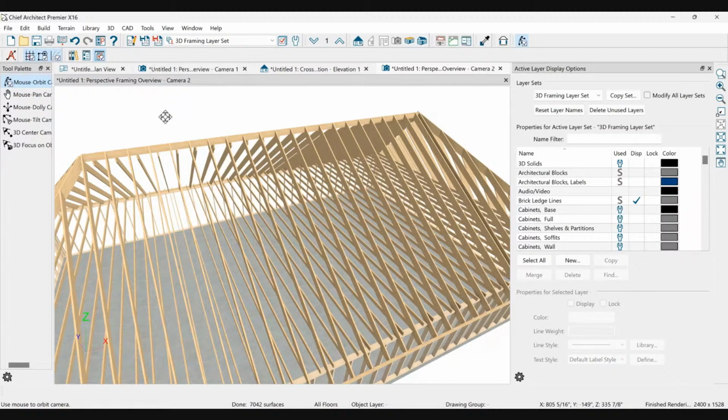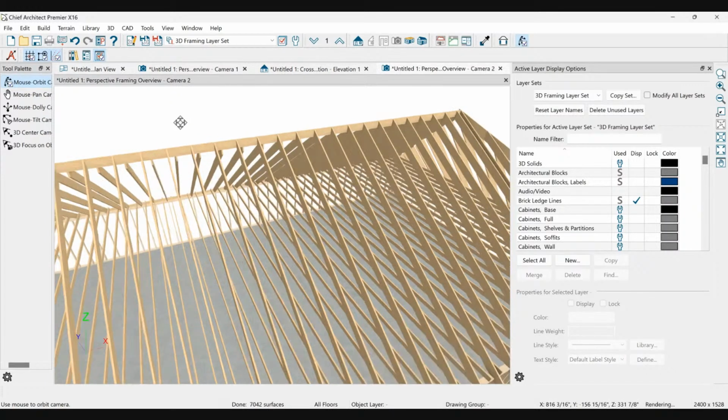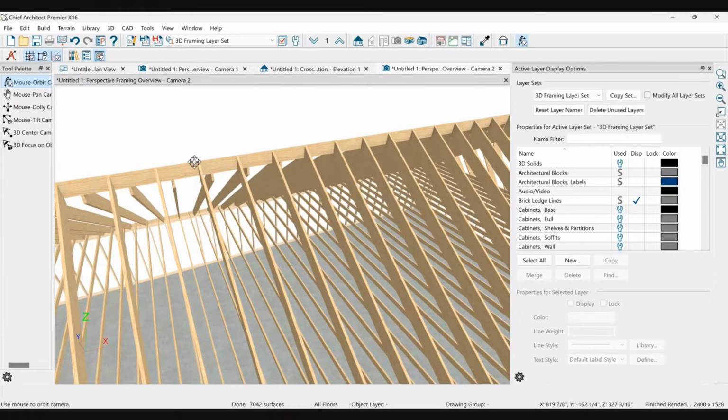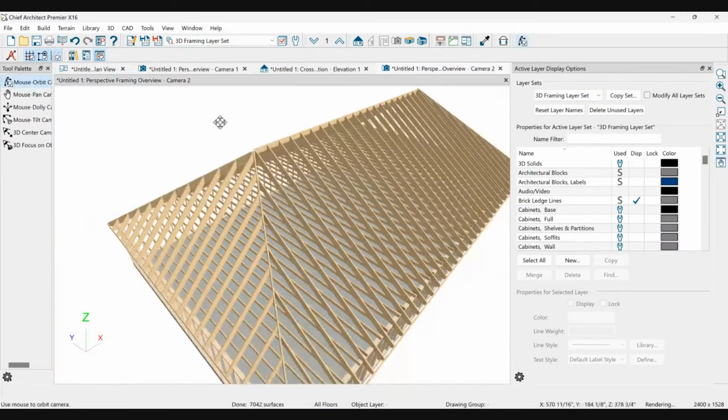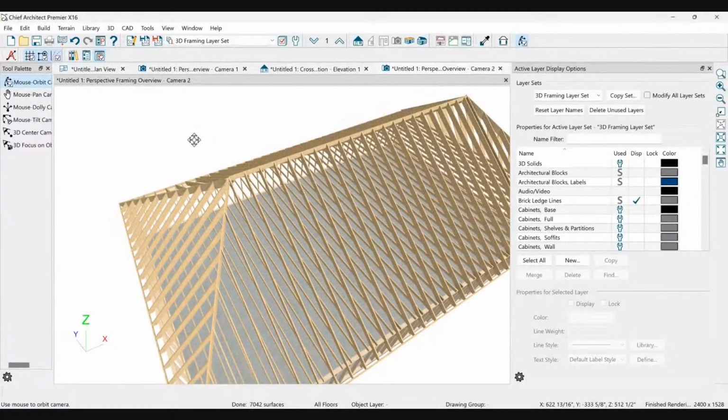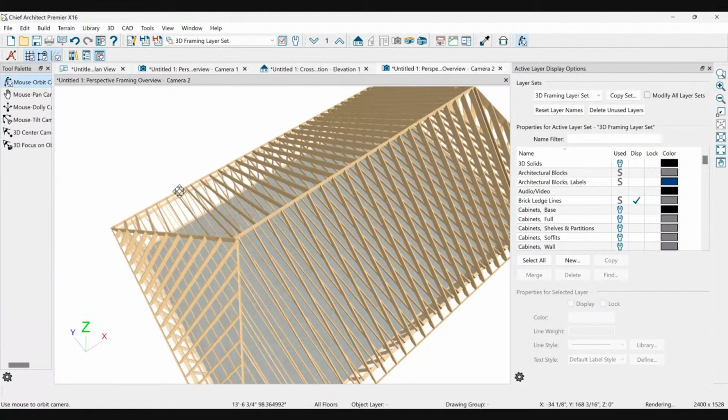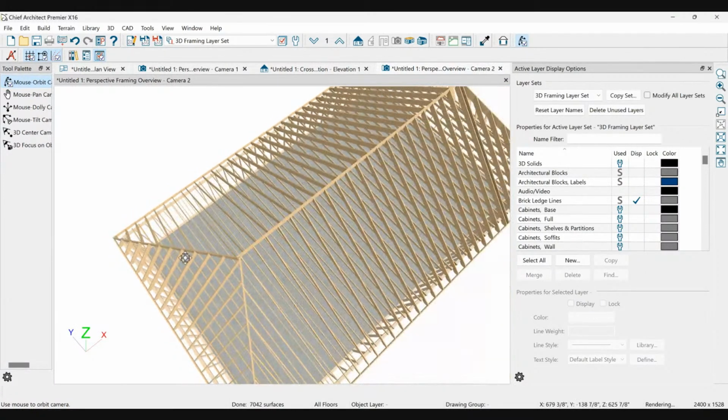So when do you use an LVL? Well, it's when your bracing gets too far apart and you can't brace, or you don't have the room, or there's nothing to support it on. That's when you use LVLs. Frequently it's going to happen in low slope areas where you can't fit beams in the ceiling area, and you just have to get a hip from one corner of the wall, like 14, 16 feet into the house. Something like that. And there's literally nothing you can do to hold the weight of the hip.